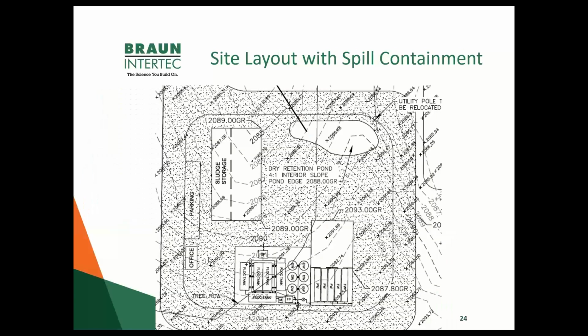So this was the site that I worked on from the initial layout, and you can see a couple different areas of materials that had to be managed internally, but the whole facility, because it had a large amount of truck traffic for deliveries, we used the exterior truck loop, raised that so that everything on site flowed to the center and could be contained in that pond.